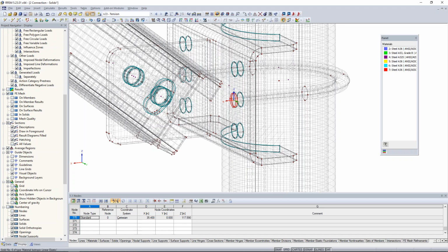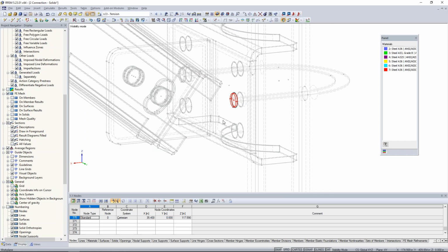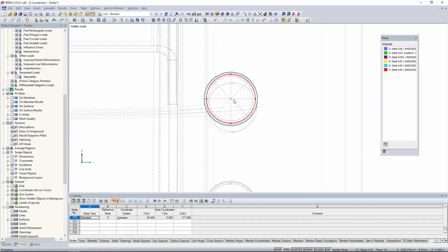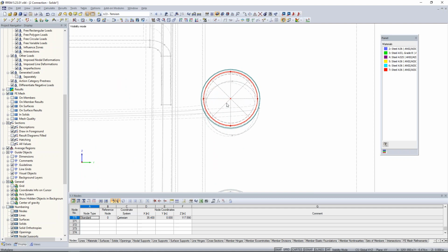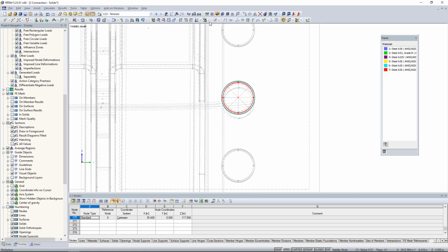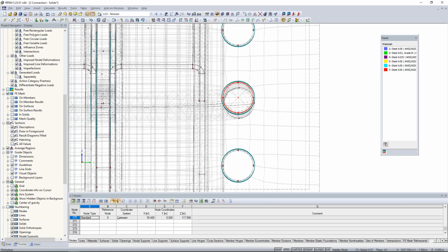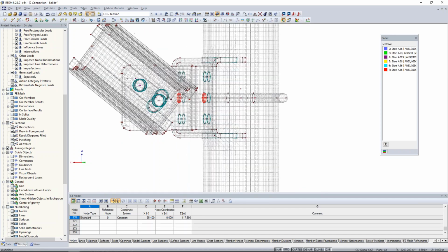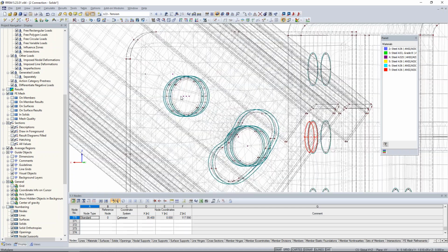And let me take a look at one of these smaller bolt solids, for example, and I'll create a visibility by the selected objects. One thing that I'd like to note when we're zooming in here is that there's actually only 2 FE mesh elements across the entire length. And if we're truly interested in the stresses in our bolt elements even, we probably want to refine this mesh quite a bit. So what I'll do here is to cancel my visibility mode, and holding down my control key, what I can do here is to select all of these smaller solid elements.